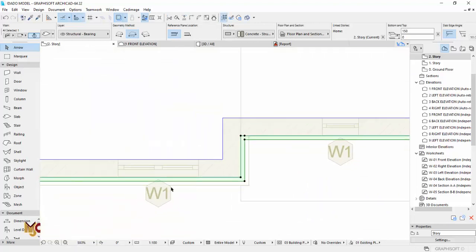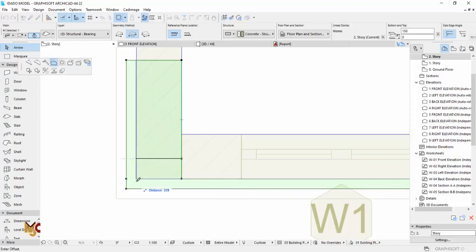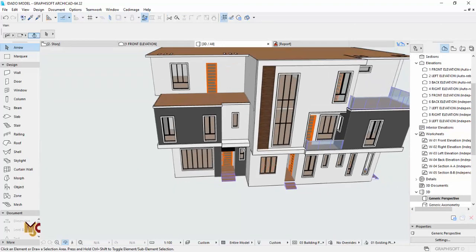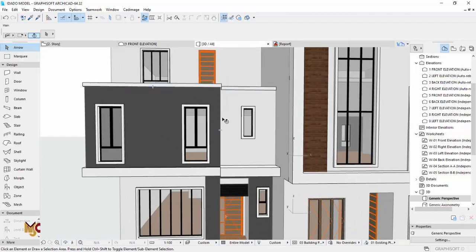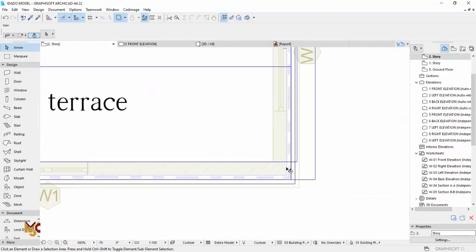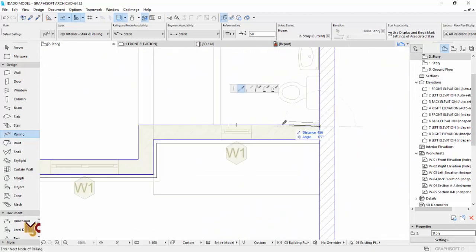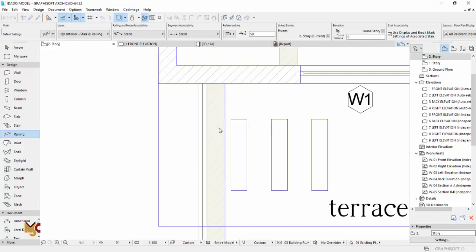So in most cases, like this, for instance, this cornices, this mold, I use slab because wall behaves a certain way. It connects with other walls. So that's why in most cases I use slab, so that it doesn't start creating some errors on what you have already done before, like what we did on the ground floor. We could easily use slab, but wall would be faster. That's why I switched the face. If you've been following from the ground floor, switch the face so that it doesn't connect.